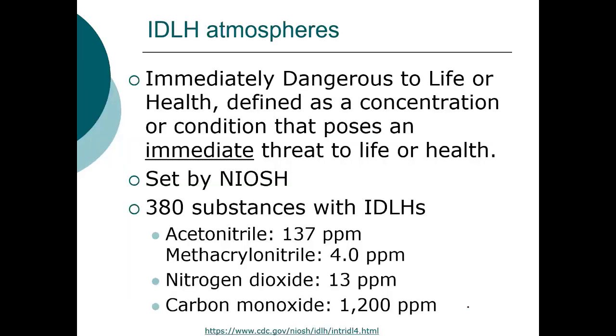And then we have what is known as the IDLH. These are immediately dangerous to life or health. Basically, get the heck out of there. These are an environment that is harmful to your health. Just being in that environment is harmful. These are set by NIOSH. So they're not regulatory limits, but they are limits that are set to protect human health.